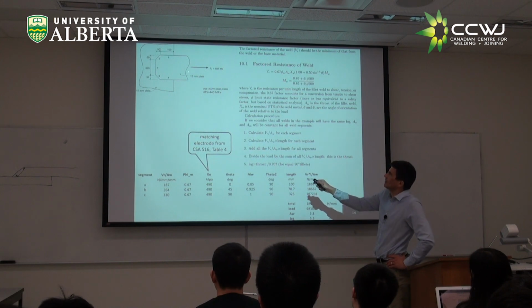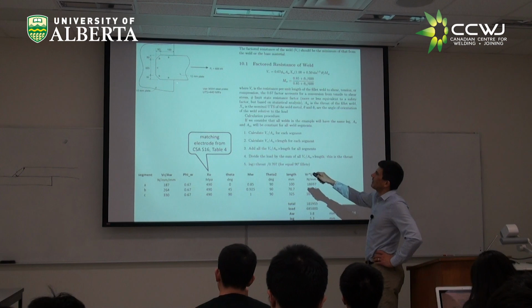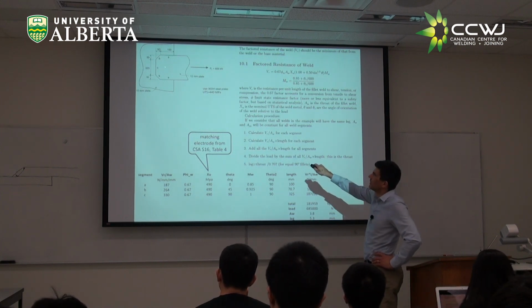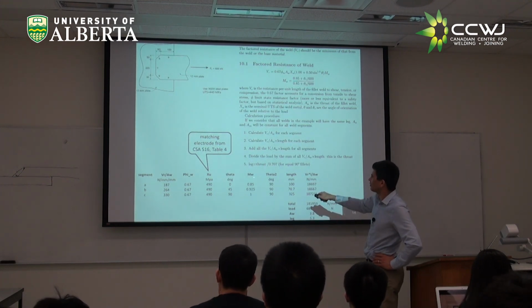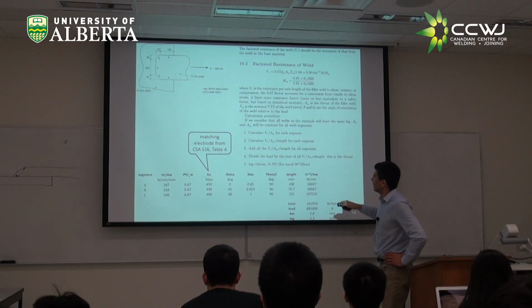That would be 0, right? Because it's longitudinal to the load. What is theta 1 for weld C? 90, right? And for B, it's 45 degrees, right? And that's what we have here. And with this, we calculate the MW, this factor.